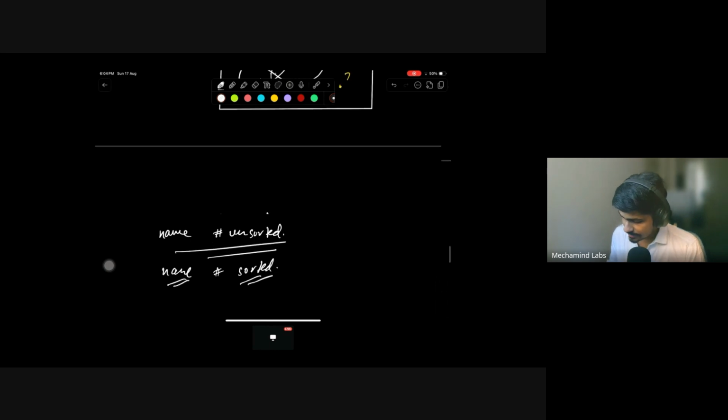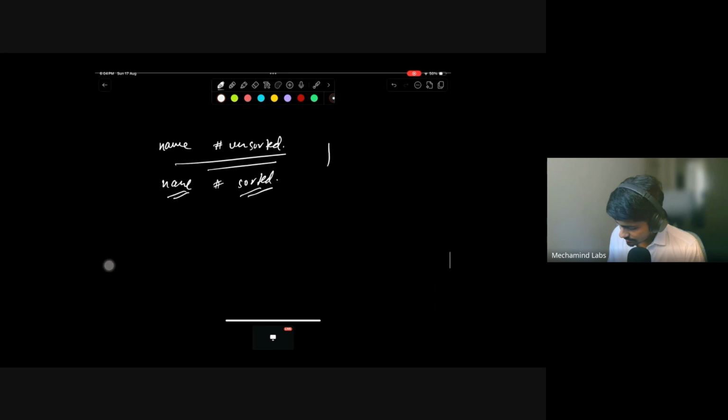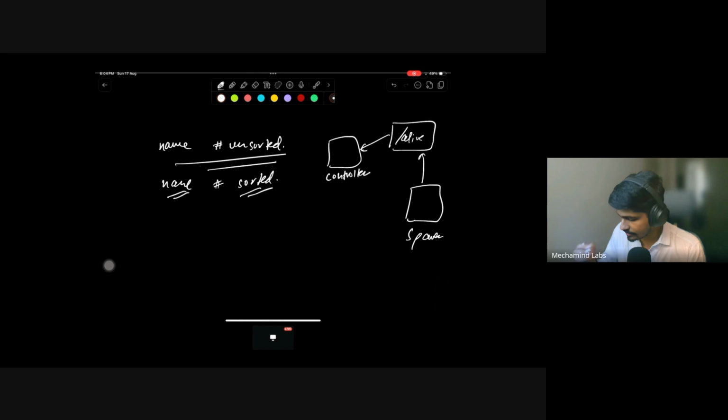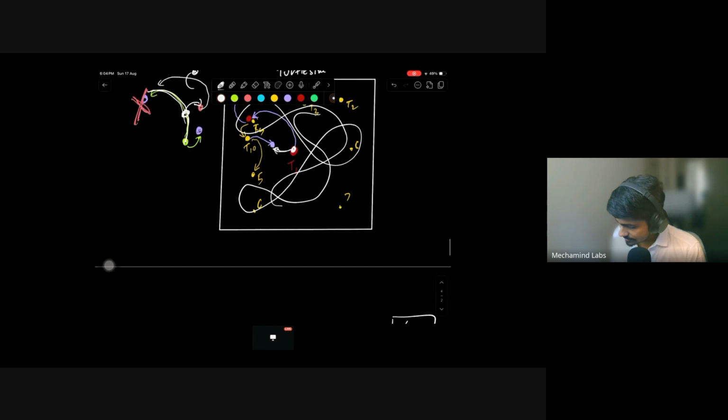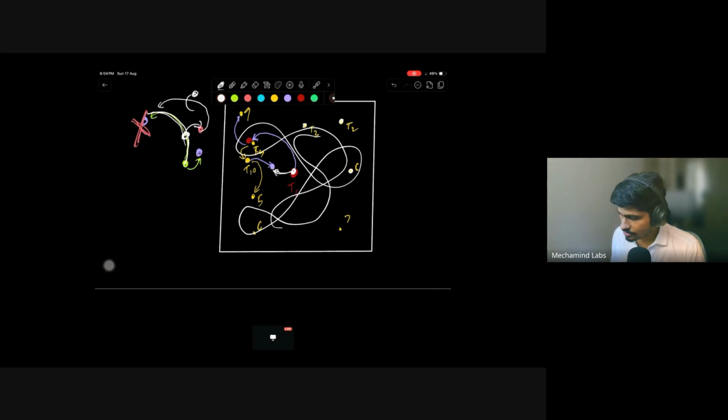Okay, similarly, every time my controller node is getting data from the alive turtle topic, it is subscribing to that topic, and my spawner node is continuously publishing the newly spawned turtles to this topic with their coordinates. So I get to know that this turtle has these coordinates, and that one has those coordinates. It will store the positions, these are the positions I have to track and move.